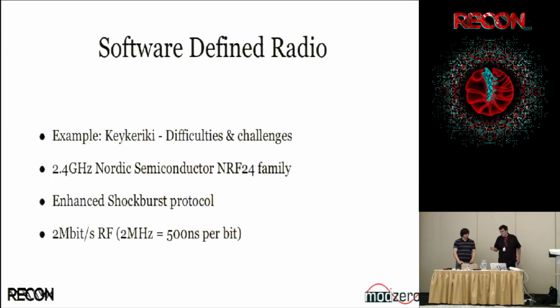So the problem is that in theory you have like 50 clock cycles with a microcontroller running at 100 megahertz, but in practice, minus all the overhead for interrupt routines, you have like 30 clock cycles for what can be done in an FPGA within one single clock cycle.